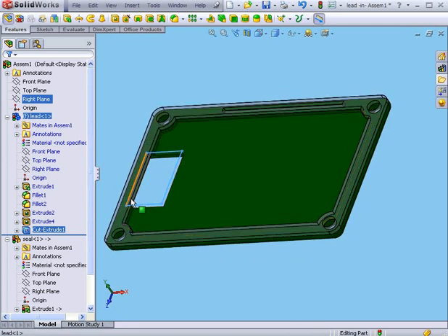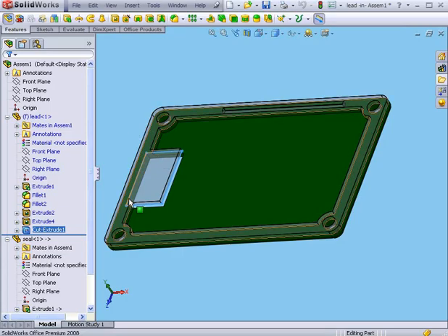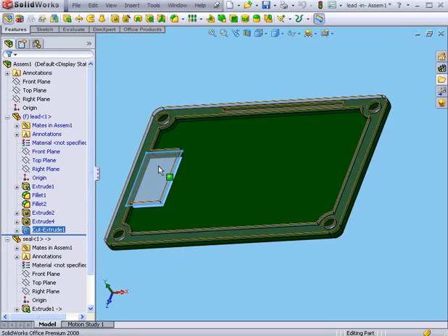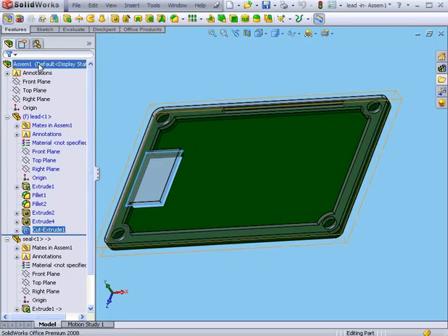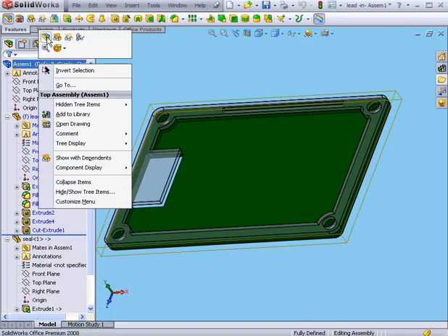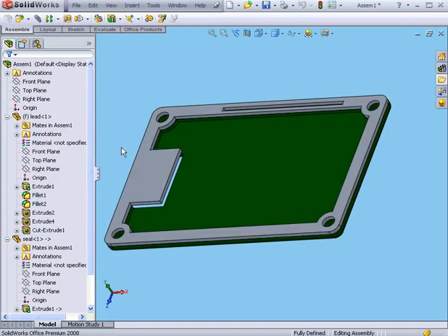I've created a seal using the part lid as a reference, and now I'm using that seal as a reference to create features for the lid. Let's click Rebuild and see what happens. As you see, the shape of the seal changed. To better see, let's go to the assembly level. You need to watch for this type of situation. Sometimes you'll get an error message and sometimes not.